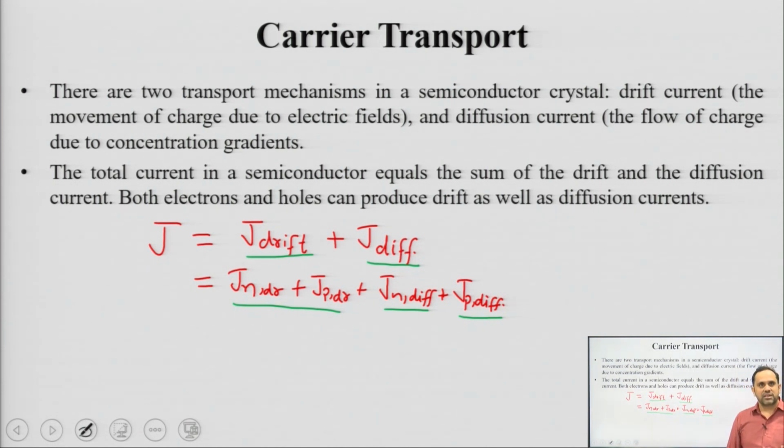So, you might have that in an N type device, only the N type drift and N type diffusion current dominates, and the other two components are so small that they can be ignored. In a P type device, the whole drift current and the whole diffusion current can dominate, such that the electron current becomes very negligible. So, in that case you can ignore that current also. Okay. But if you want the complete value, the whole value, you will include both drift as well as diffusion, you will include electron and hole diffusion current, you will include electron and hole drift current also.